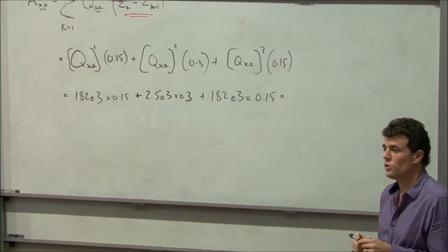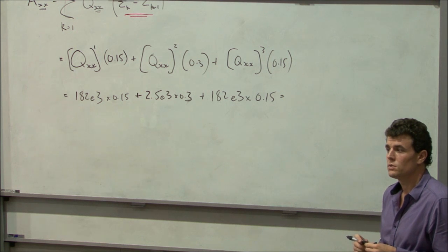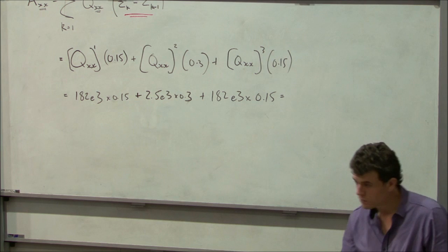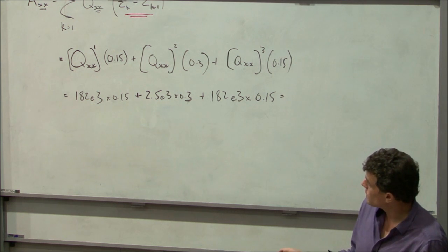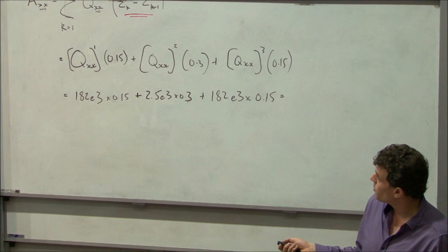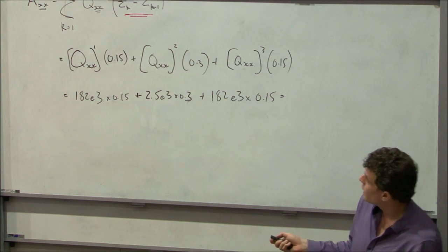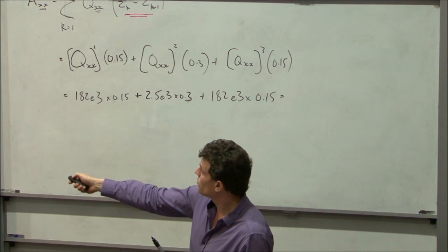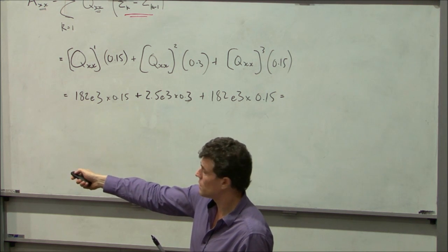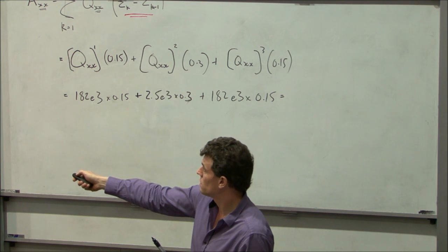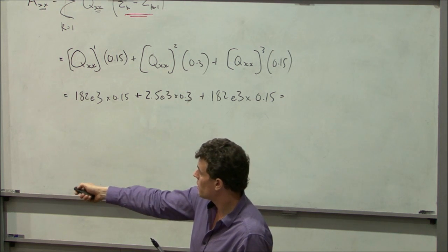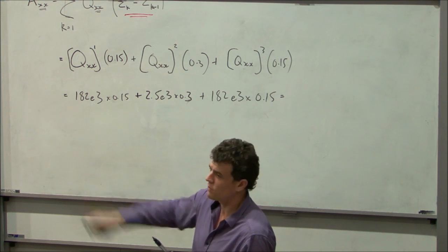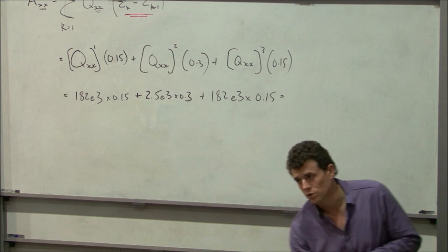That's a good question. What are the units of this? Okay, let's have a look at how we use them. Up here we've got force per unit width, so this is newtons per millimetre. Here we've got strain, which is dimensionless. So the units of A have to be the same as the units on the left-hand side, so it's newtons per millimetre.